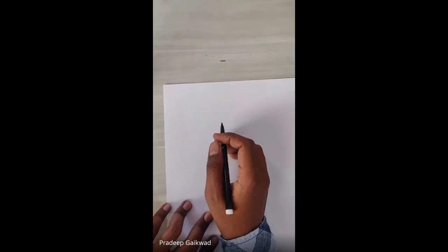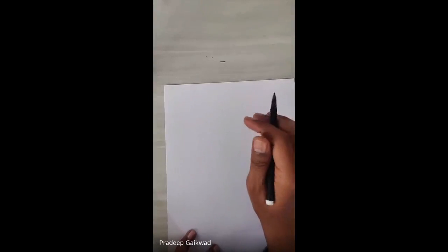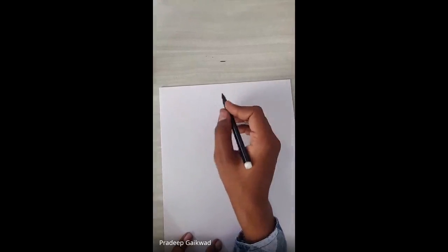In yesterday's lecture, we talked about the Chebyshev spacing method, and I discussed one formula with you. Anyone remember that formula? To find out precision points: xj is equal to half of (xs plus xf) minus (delta x upon 2) cos phi, where phi is (2j minus 1) upon 2n. With the help of that formula, I can find out precision points x1, x2, x3, and so on. Also, if x is known to me and y is equal to f of x is your function, then I can find out y1, y2, y3.